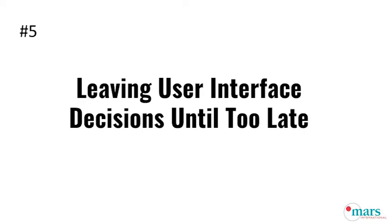Sometimes you want to make those user interface decisions as early as possible, particularly if they're going to inform your mechanical design. But if you're not sure about a user interface decision, I highly, highly recommend trying to do mock-ups as early as possible. As soon as you can get something into your own hands or the hands of prospective users, even if it doesn't do everything you need it to do, it's going to go a long way towards helping you understand what's working and how people interact with the product.